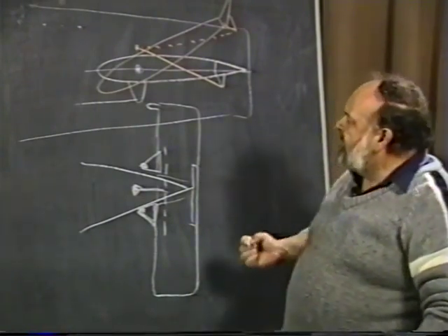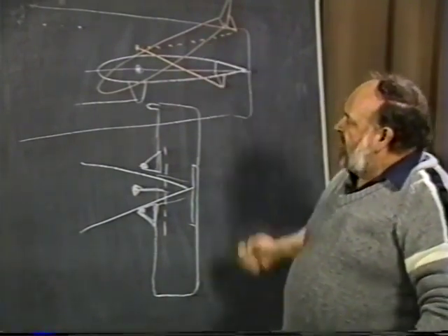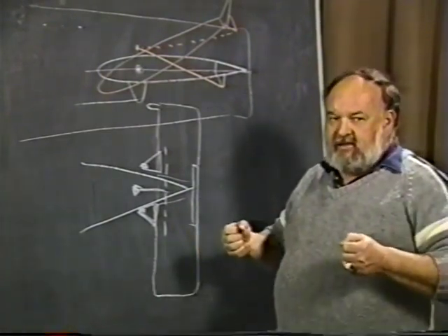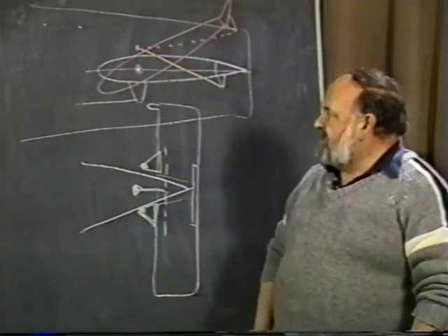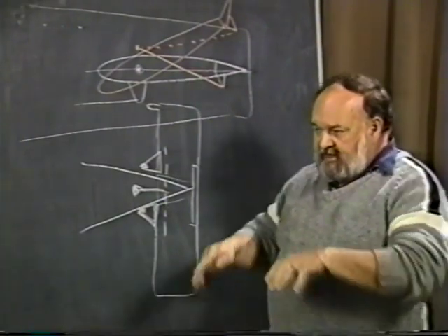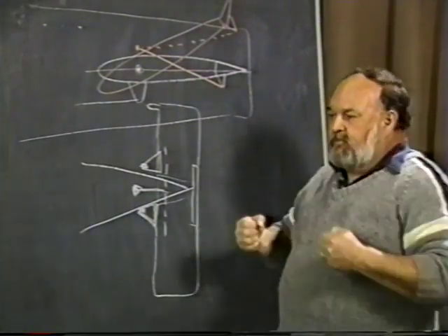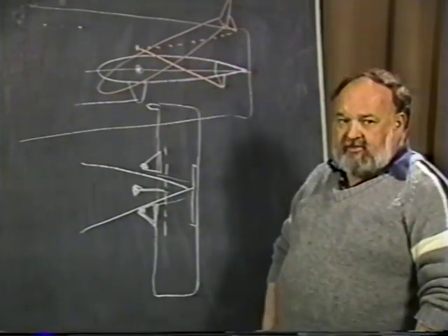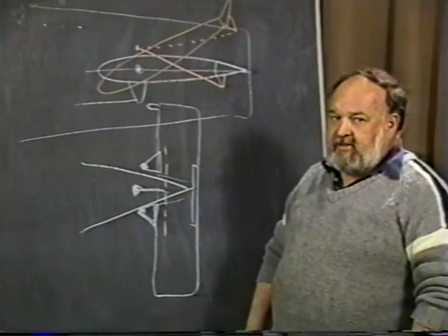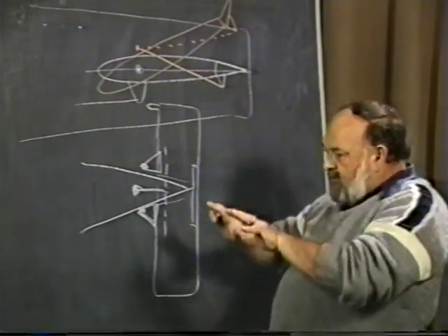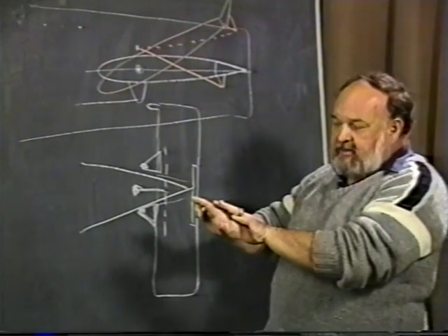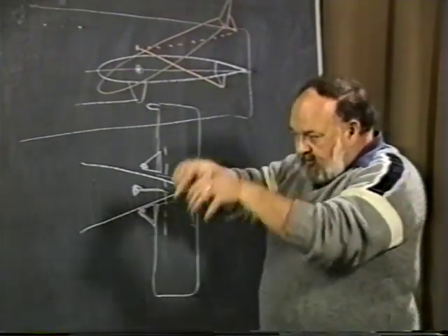Why is that important? Well, if you have this all-flying tail and you get to a condition where you can pull the wheel back so far that you cause the tail to stall, and in most cases, this is when you're coming in for a landing, you pull back on the wheel, the tail starts to go down into this position. If it stalls on you, you've got a real dangerous situation here, because what happens is this big download that you want to pull down on the tail now disappears. The tail is stalled, inverted, and it pitches up, and the nose comes down.